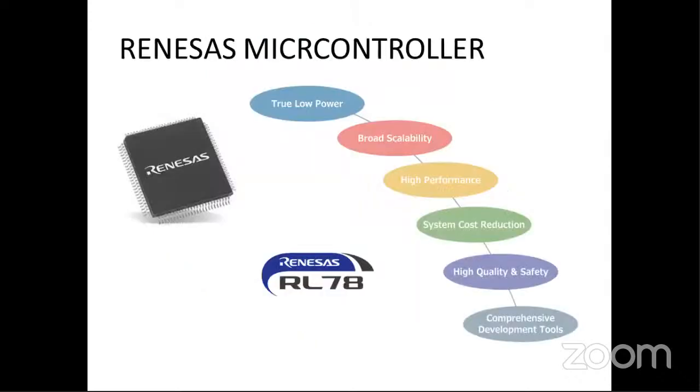Now, this is the core of our seminar, that is the Renesas microcontroller, and the family we are going to look at is RL78. Basically, the Renesas RL78 is a 16-bit controller. This controller supports CISC architecture and Harvard architecture. It supports 3-stage pipelining.